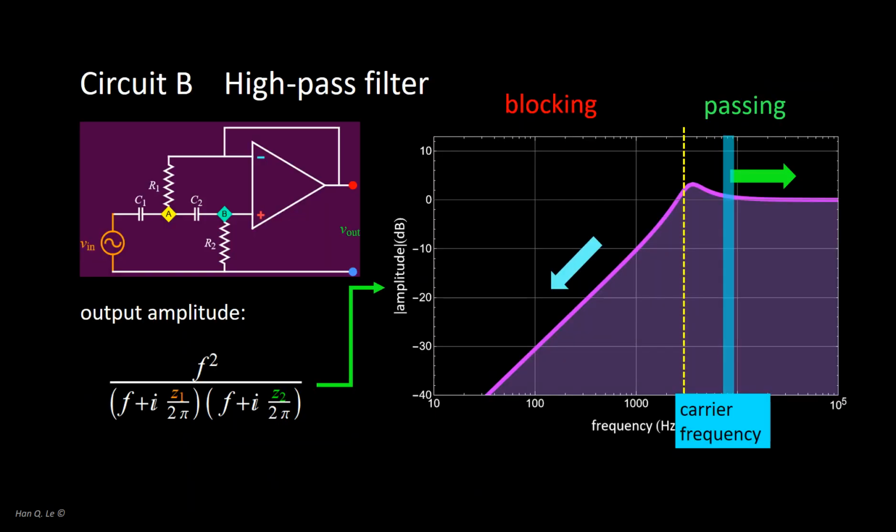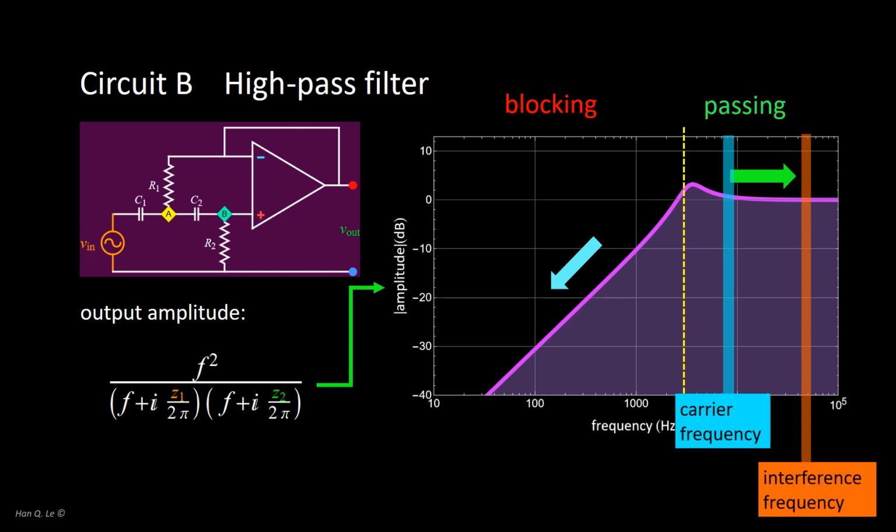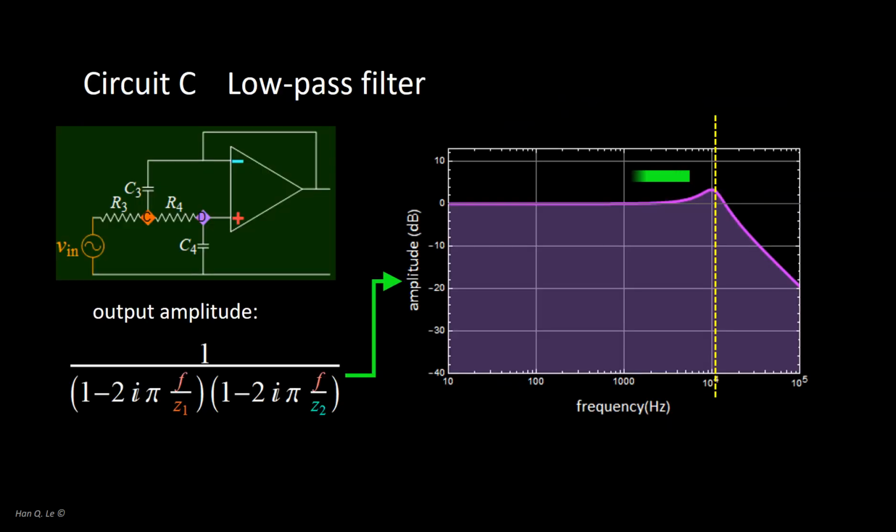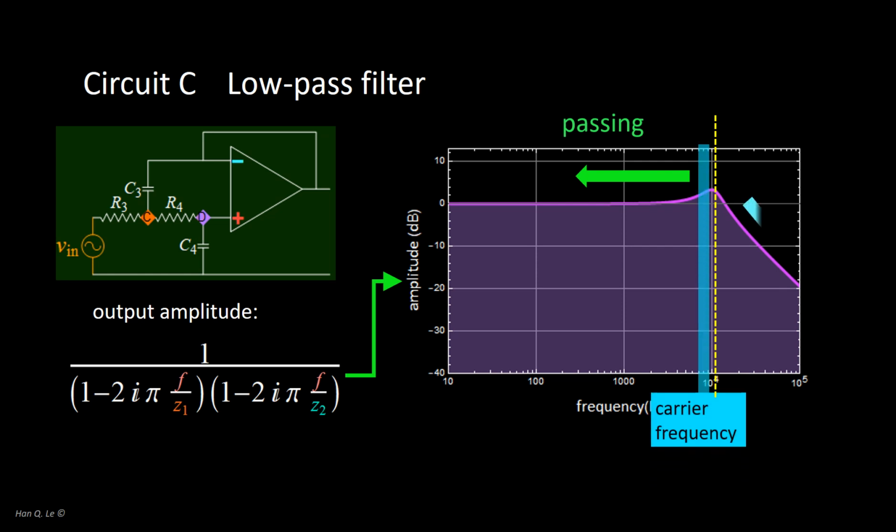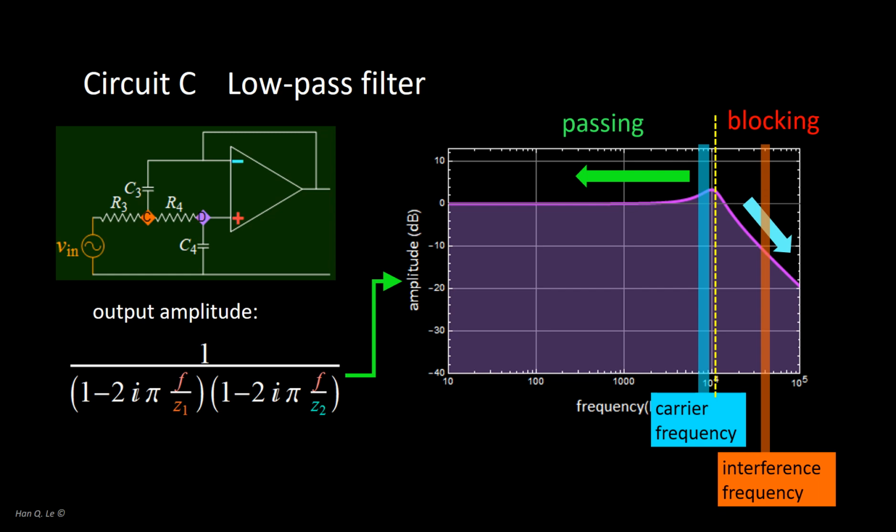The reason is simple. The interference data has its carrier frequency, in this example, around 40 kHz, hence, both the signal of interest and the interference can pass through the high-pass filter practically intact. What is needed is a filter that allows the low-frequency signal of our interest, but blocks the high-frequency interference. In other words, a low-pass filter.